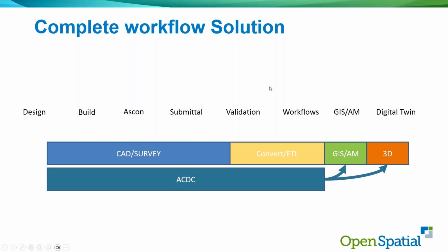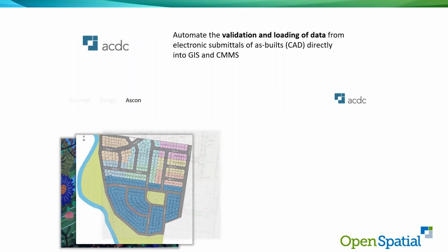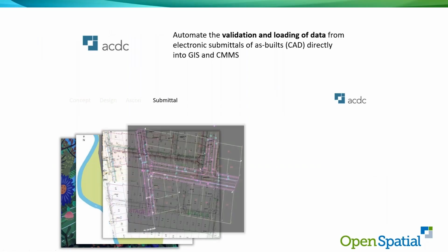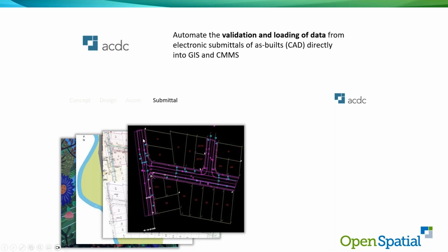So you've got to figure out how those work. If we look at this little cameo, we start with the CAD. You use those tools on the toolkit. We do a whole submittal process, which includes all of the validation: closed polygons, isolated nodes, snapping and breaking, to create a full segmented model, with all of the attributes and range values, domain values, matching the GIS.